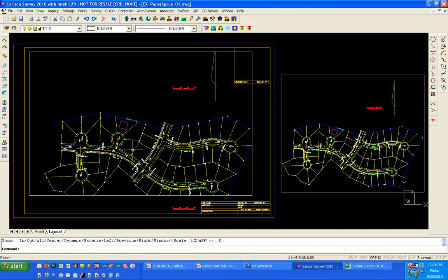Now, when I switch over to AutoCAD, I'm going to show you AutoCAD has a much easier way to set that standard scale. I think that what I've just shown you here is still the easiest way. You can do both of these. You can type in Z and then 1/50 XP in either IntelliCAD or AutoCAD. That's kind of the old manual way to do it. That works in both. And that is still probably the easiest way to do it in IntelliCAD today.